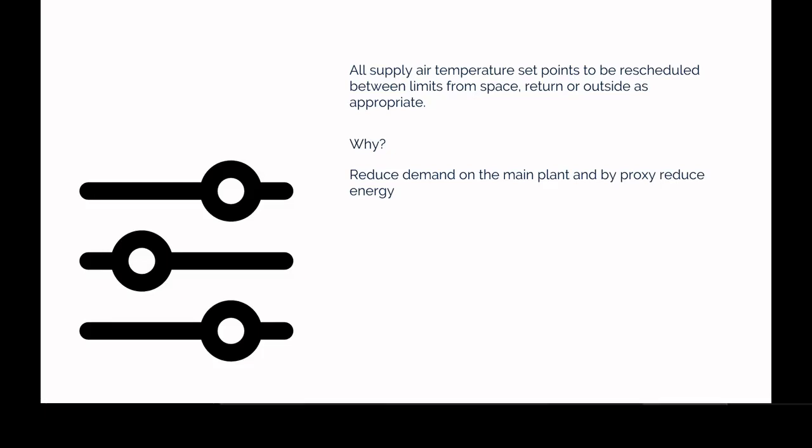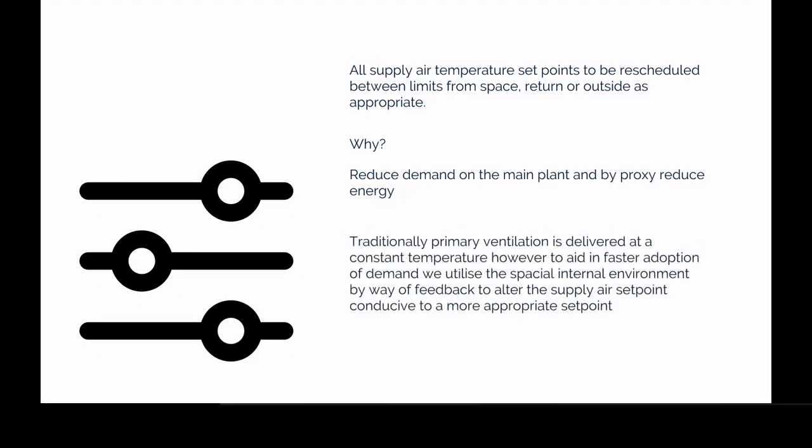That's going to aid the requirement for the main fan coil units, whether it needs more heat or more cooling. So you can range that between a minimum threshold and a maximum threshold to get the right level of data and the right level of demand.